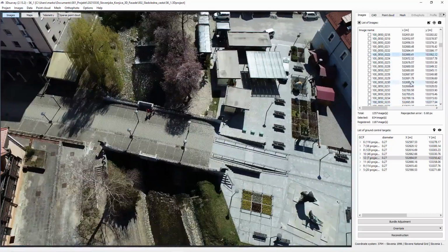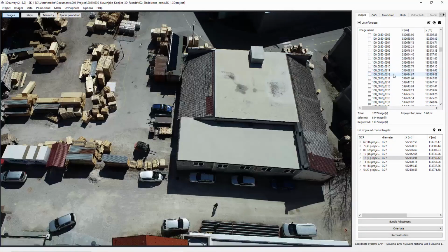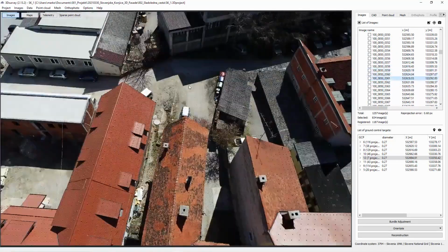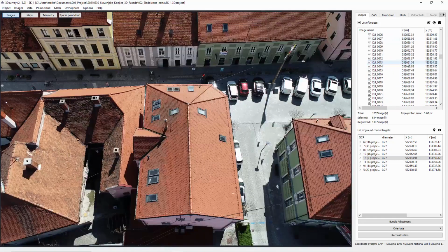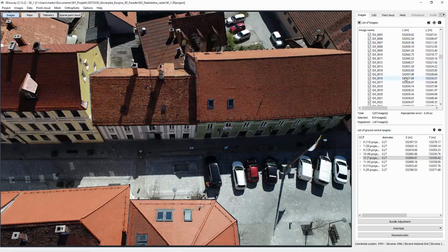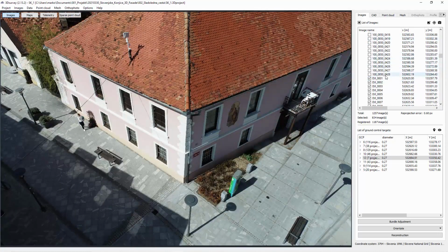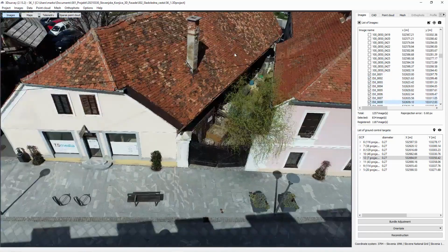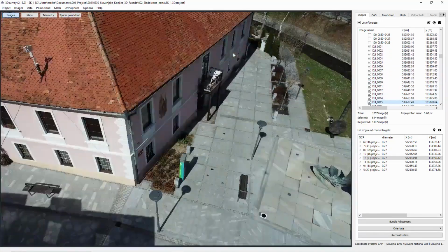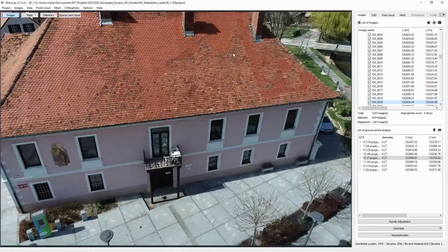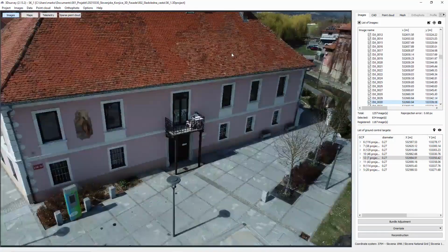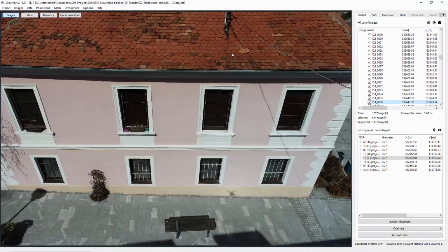And then when I start with my manual flights, let's go a bit further down. Here we are still okay. I think no, still double grid. Okay, here we can see by the name. So this was the planned flight mission, and here DJI 001 I start with manual flight. And as you can see, I try to fly parallel to the road, turn the gimbal angle to, let's say, 45 degrees or something like that, and just trigger images every 2 seconds or so.